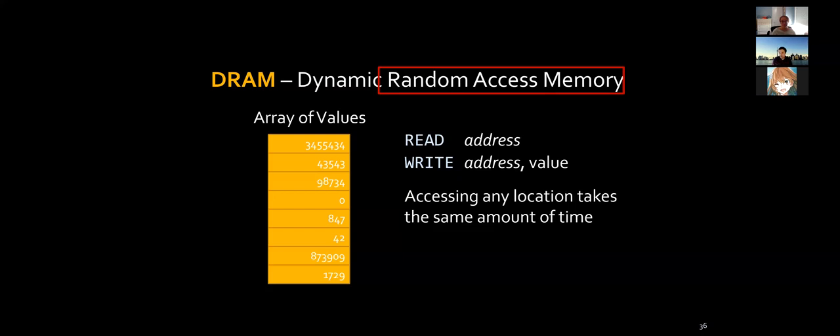RAM takes the same amount of time for any index, but for register, this is not the case, right? No, SRAM is also, we try to organize it so that it takes the same amount of time. That's part of their design of the register file and cache. We're going to organize it so the latency is going to be the same. Again, to avoid the nightmare of dealing with variable latencies.